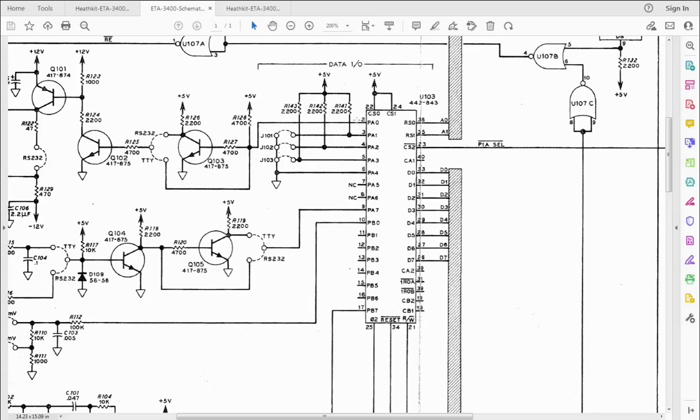So this is very much like drawing an image on an Atari 2600, and then the processor has to do all the timing to take a byte of data, separate it into bits, and then send the proper bit level out for the proper amount of time for a bit clock for the other side to recognize it and receive it, and then of course reassemble it as a byte it's received.